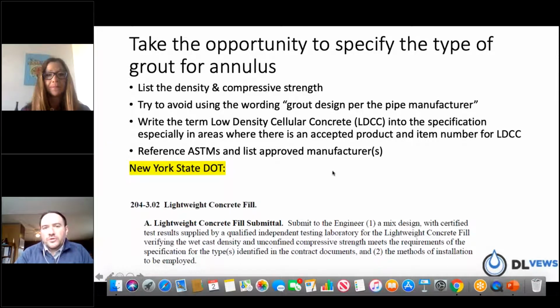Again, there's been folks and owners and installers who've had success utilizing flow fill right off the back of the ready mix truck in shorter applications, right? So on your average street culvert where you have some time and it's maybe 50 or 60 feet long, I don't want to generalize and say all, but most of the time flow fill should work okay. But once you start climbing above that 50, 60 foot mark, it can present some challenges.